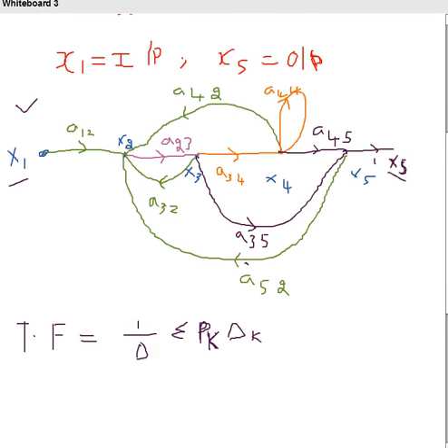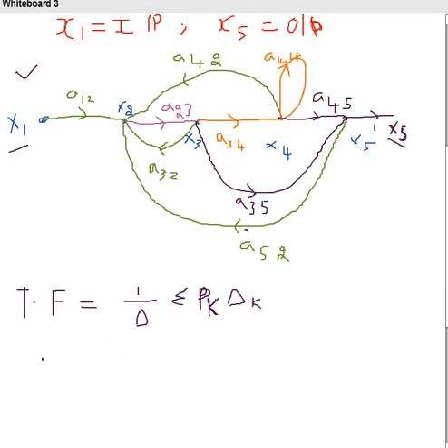Two paths are there. So what are the path gains? K represents the number of paths here, since there are only two paths. See the arrow directions also. So this is one path. So K represents 2, since in this problem two paths are there.